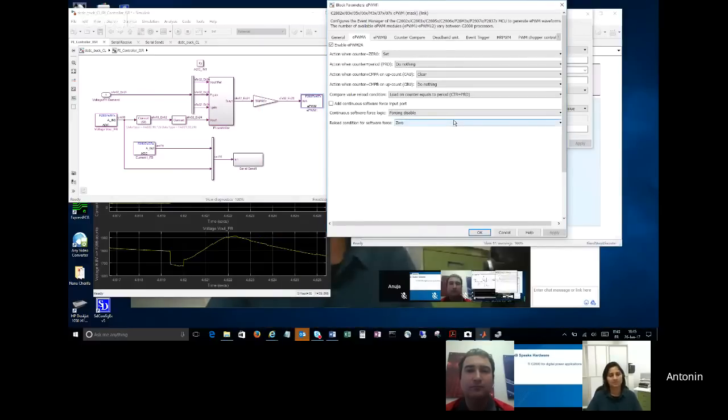So I enable PWM2A. When the counter equals 0, I set the output. And when the counter matches the compare A, I clear the PWM2A. So if I pick an example, if my input is 250 counts, for example, it's going to be set for the duration of 250, and then it will clear for the remaining 750 counts. So I get 25% duty cycle on the upper leg.